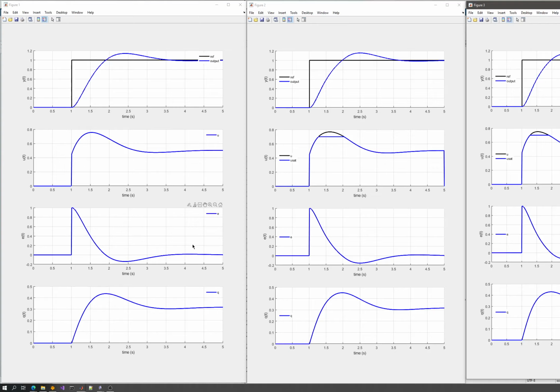So don't think of PID controller design as only dominant pole placement, because it's not only about poles and zeros. Most of the time, it is also about the control signal itself and the restrictions of the system. And since the real world is not linear, but only linear at certain equilibrium points and operating points, or we are linearizing most of the systems at operating points and equilibrium points, this means that we will definitely have restrictions on some of the signals and internals of the system. So keep that in mind, and it's very important to check out the controller and have info about the system or the process or the application itself.